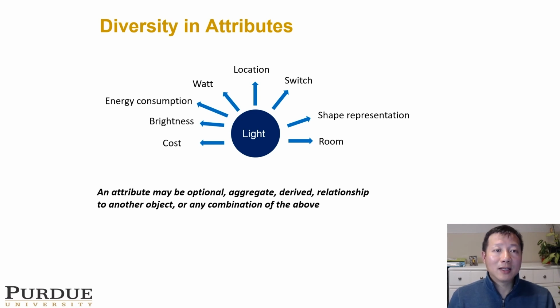What we have just seen is just one set of the attributes that specifically refer to this shape representation. As we mentioned, every object has a shape, right? Because in your BIM, in your building models, every object has a shape, has a geometry, has a location. So all the dimensions we just saw only represent the shape representation here. Apparently, this tells me that this shape representation is actually viewed as an aggregate type attribute.